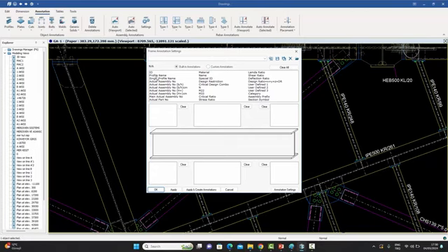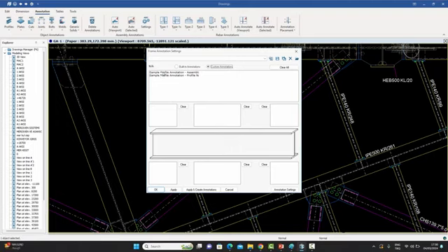So if you want to use the existing off-the-shelf ones, you can just do so by dragging in. So you can, for example, say I want the profile name and I want the material name, etc. But if you want to use the custom annotations, then you clear them, you leave these empty, and you go to the custom annotations place. And now when you do that, you see you've got two new custom annotations which are used for profiles. You can, of course, go back to the file and add as many as you want. So let's basically take this and add this over here. This is the sample profile custom annotation. It basically gives some assembly part number or something like that, and you apply it.